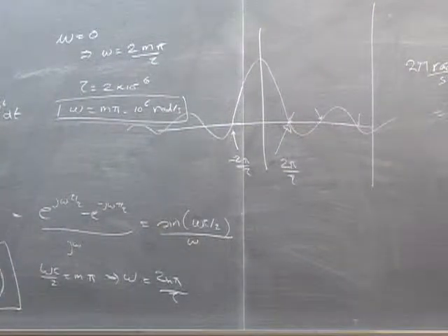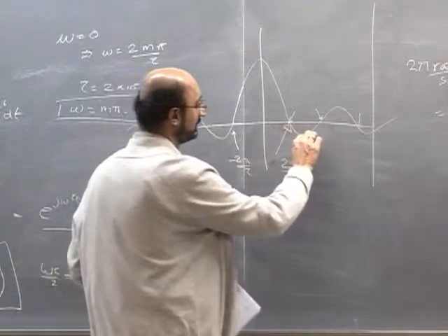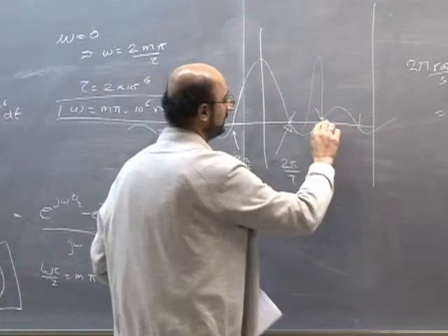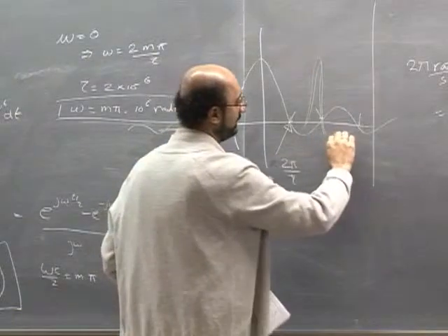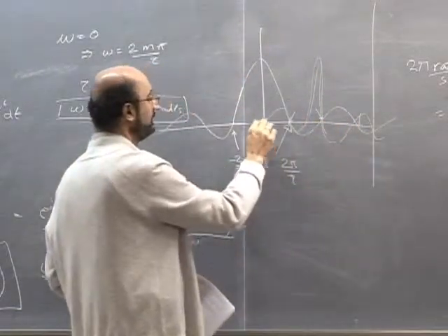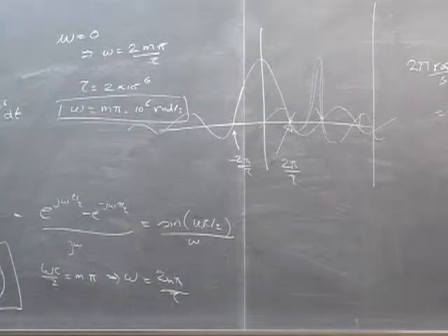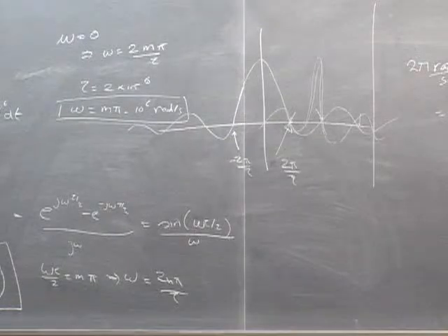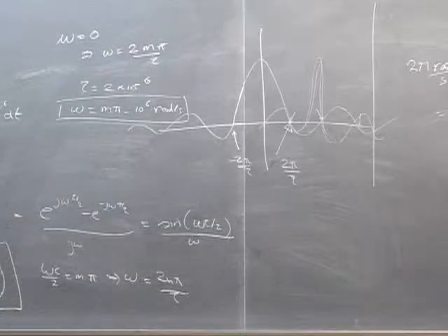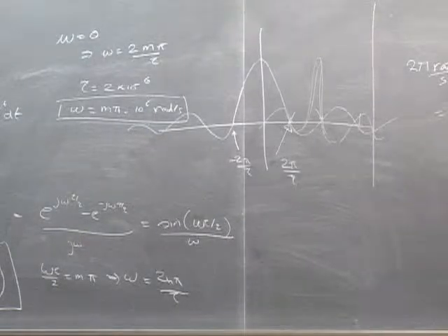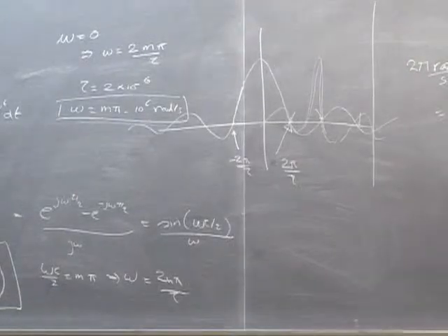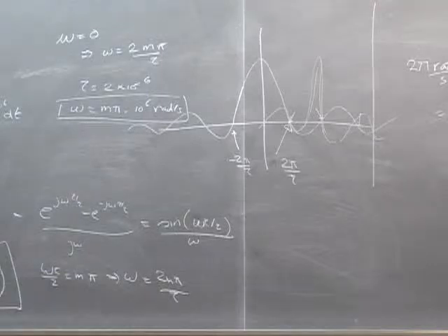Okay, which means I can put in another signal, something like this, another sync pulse, which is centered over here, and what will happen is its energies will be such that they're centered at the 0 points of this particular pulse. I'm not really drawing it very well, but intuitively what's happening is that the pulse, which lasts 2 microseconds, in the frequency domain has these frequencies which have no energy. So I can put a pulse in there, with that carrier. I can put a carrier in that range. When I put it there, it's not going to see the other one because it's just kind of invisible.